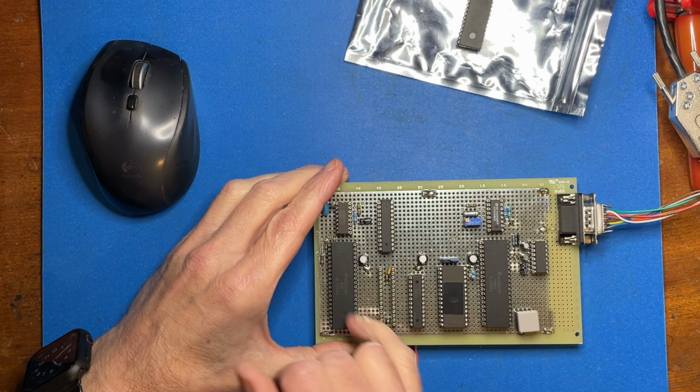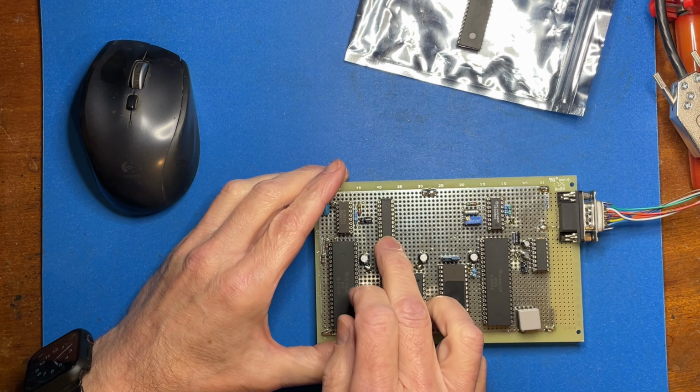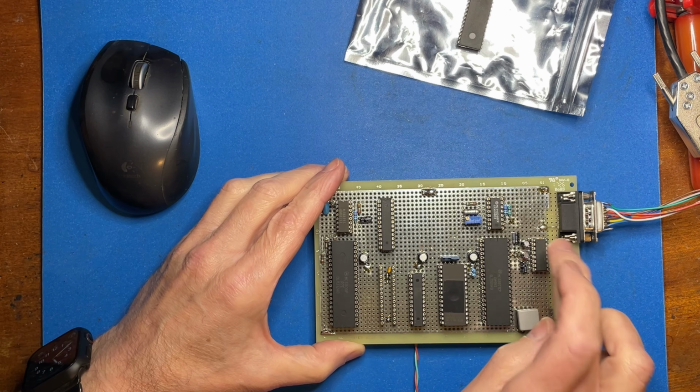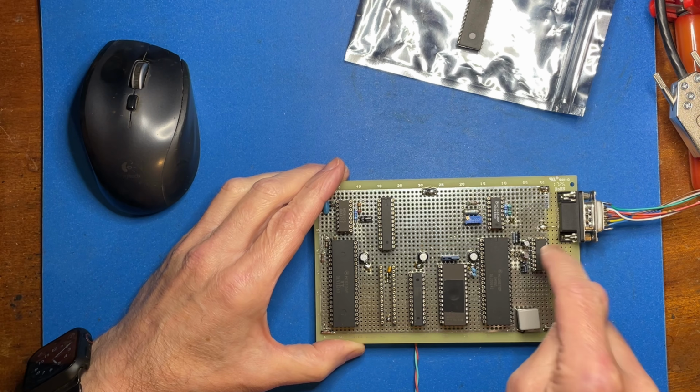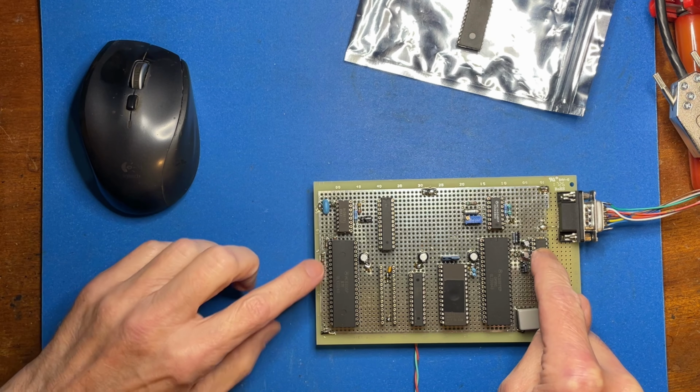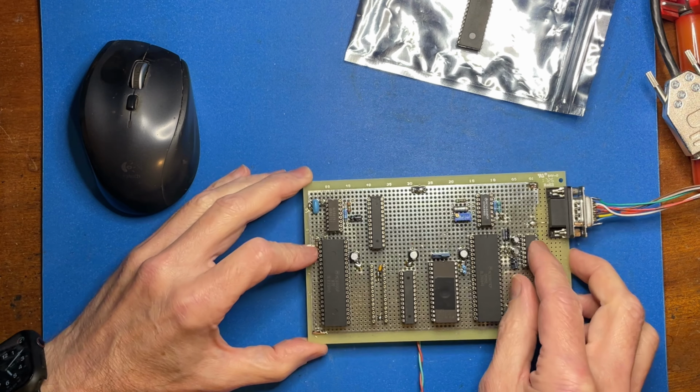I think I got to the point of letting the processor run and check the decode by seeing if there was actually worth trying to talk to things. But I'd not put the links on to the actual Max 232. We'd also left some pull-up resistors off down here, which could have been causing spurious interrupts.